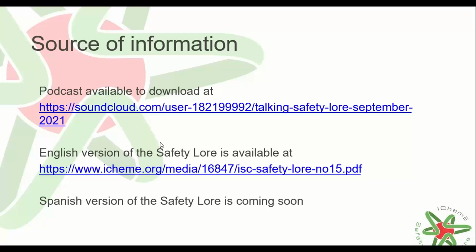So earthing and grounding have a really important role in this regard. I think it's really crucial. And also ventilation, fans that are ATEX or any other equipment that you use, like torch and all the other equipment should be specific to this particular hazard.